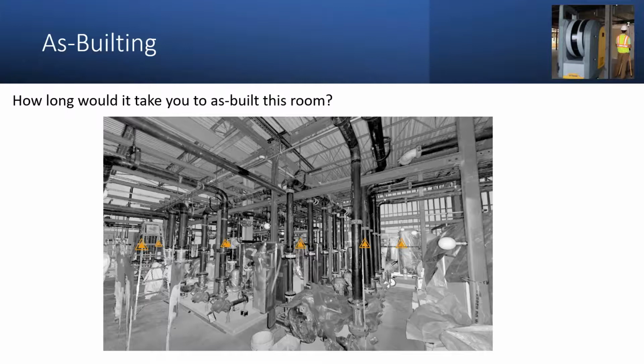So question. If you look at my picture here and you see an MEP room with a whole bunch of piping and a whole lot of pumps, the question would be, how long would that take you to traditionally measure and as-built that? You're typically using ladders, measuring tapes, scaffolding, lifts, whatnot. It would be days, if not weeks, to measure that type of environment. That's why we have laser scanners now. We can go in and as-built a room like that in a matter of hours, and then have a complete data set that we can measure from any point to any point within that room.